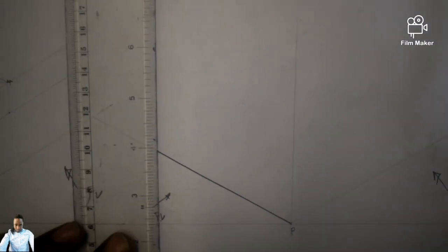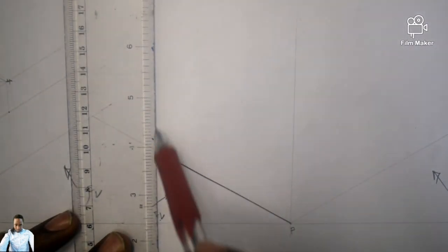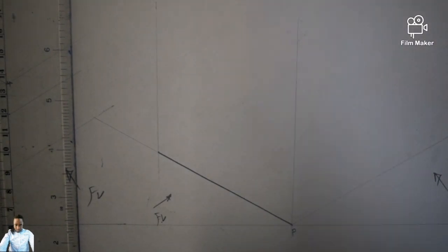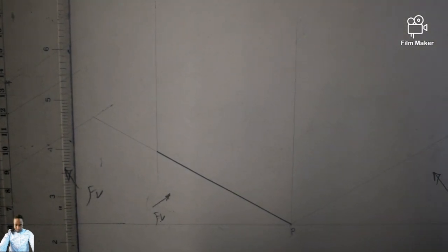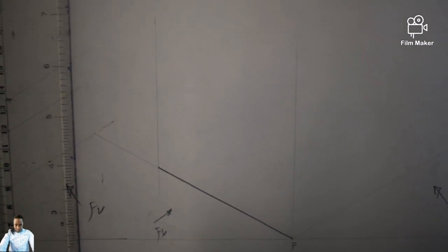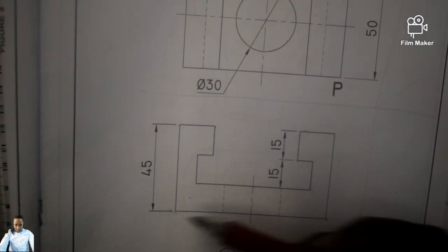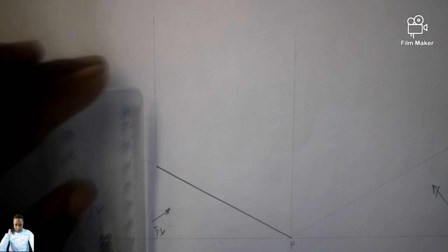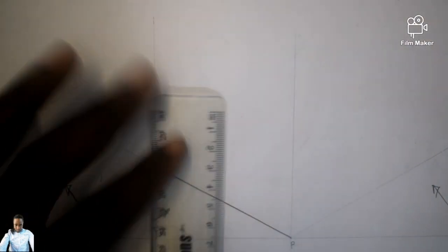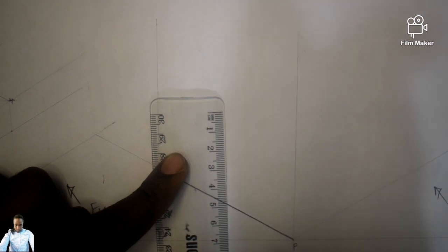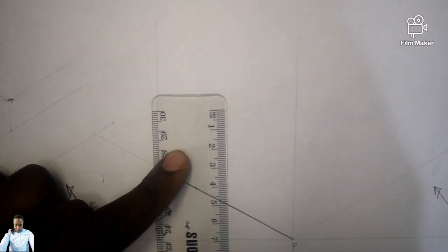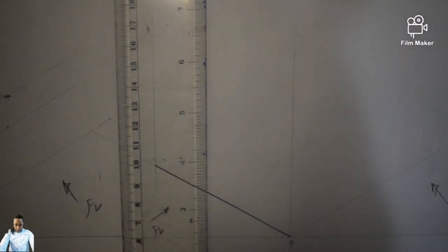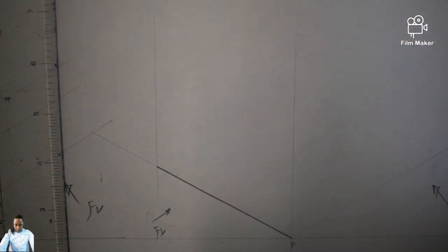So now I can go up faint. Why am I drawing faint for now? Because I am not yet sure how high it's supposed to go, until I come to say, okay, it is 45. Then, on a well recorded line, I record a dimension. You'll see students doing it otherwise, but it's wrong, because what if you are not accurate? So you must firstly get a faint line recorded, then on top of that correct line, you can record a dimension, you understand?